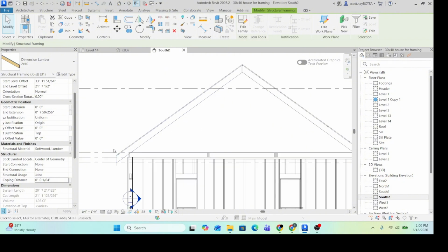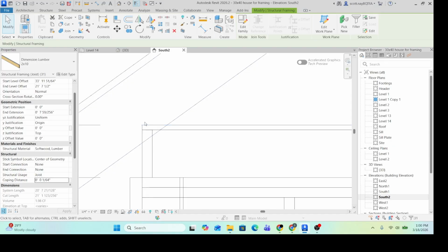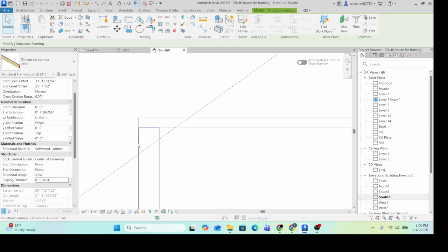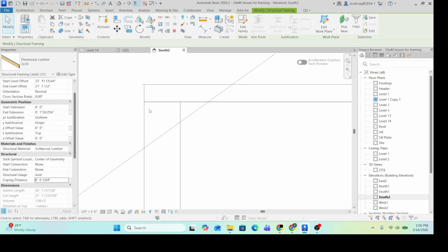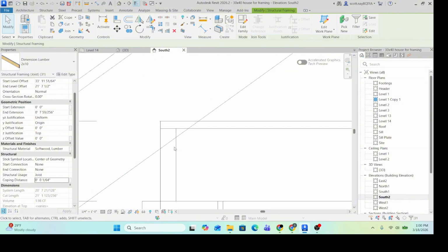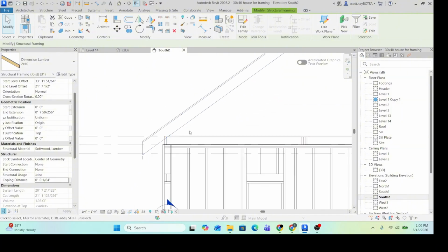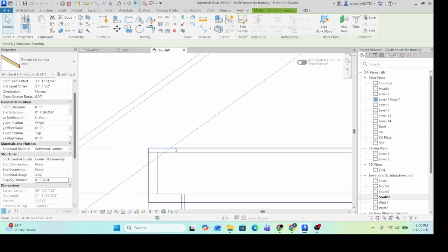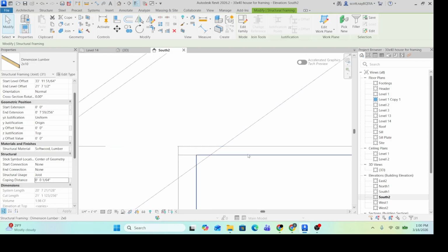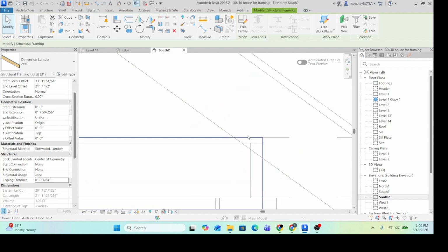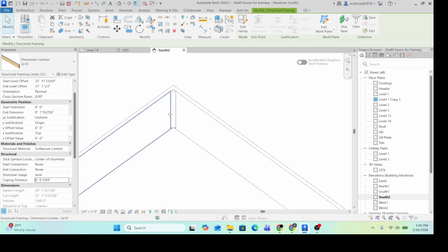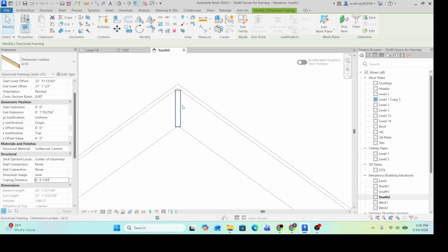So before I do the gable wall video, if you wanted, you could also cope to this. Unfortunately, because our subfloor is not a beam, it won't cope to that, but you could theoretically do another cope for this and for this because they're also beams. So if you really wanted to and you broke this into parts, you could peel this back and cope your bird's mouth on this side and on this side. It's the same process as up here. I went ahead and did these, but